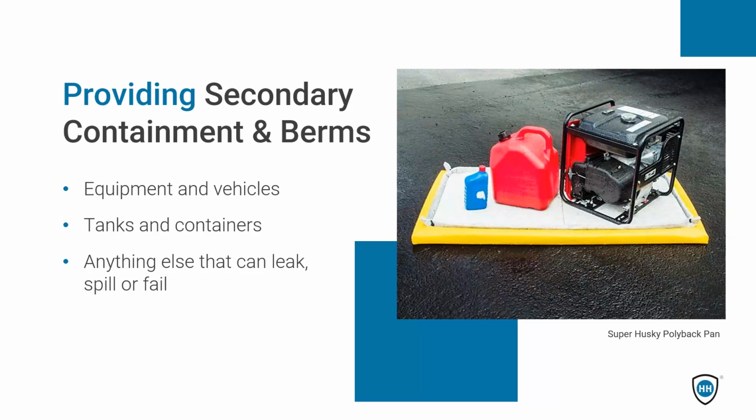If you've got a lot of portable equipment that's stored outdoors and it doesn't make sense to move it all inside, perhaps putting a berm around that area. Maybe you have fluctuating inventory levels and you get a lot of equipment or tools or supplies or product in for a job and then it goes away. There are a lot of different ways to do secondary containment now. It can be done with earthen berms. It can be done with portable systems.